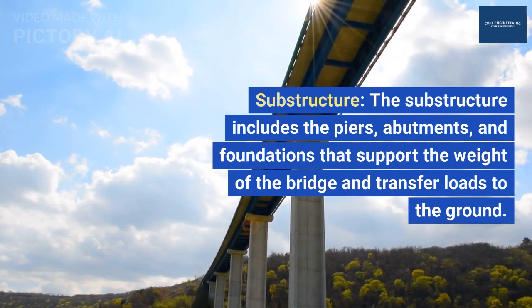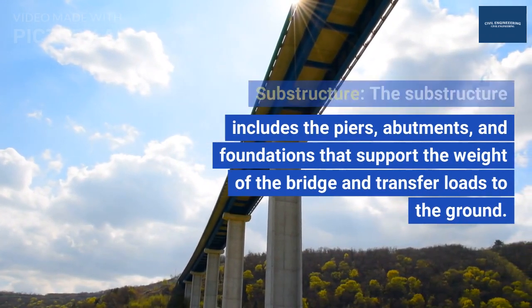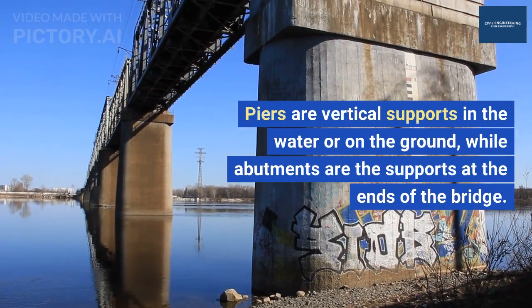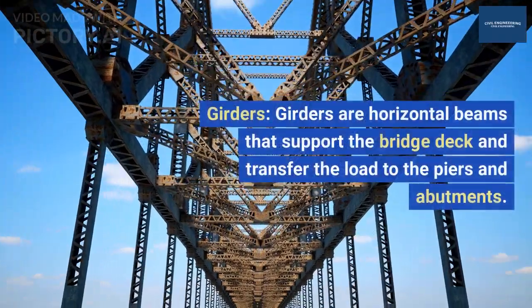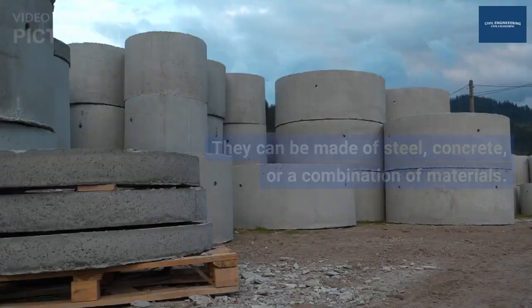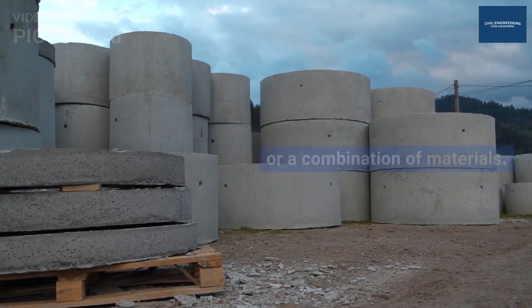Substructure. The substructure includes the piers, abutments, and foundations that support the weight of the bridge and transfer loads to the ground. Piers are vertical supports in the water or on the ground, while abutments are the supports at the ends of the bridge. Girders. Girders are horizontal beams that support the bridge deck and transfer the load to the piers and abutments. They can be made of steel, concrete, or a combination of materials.